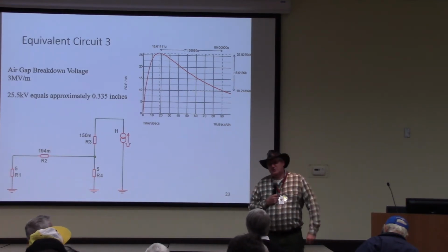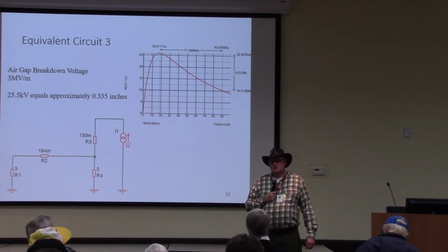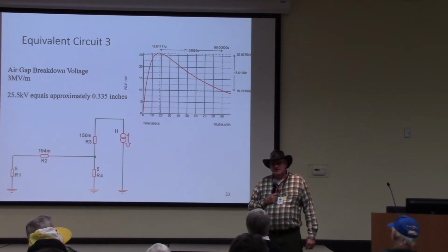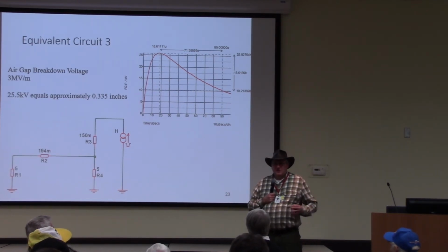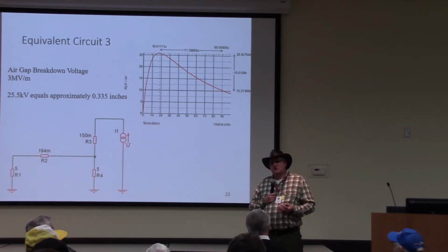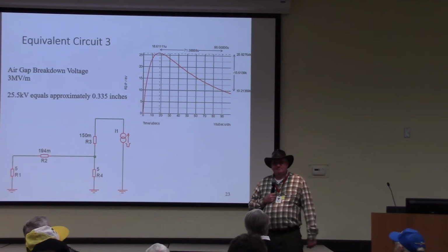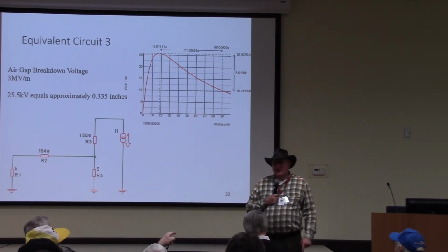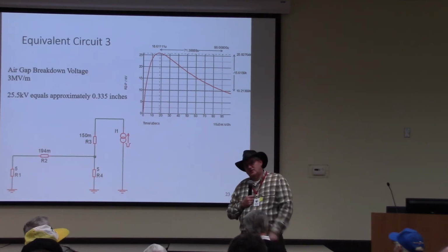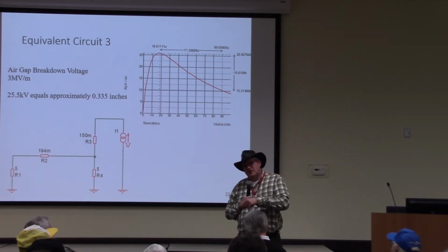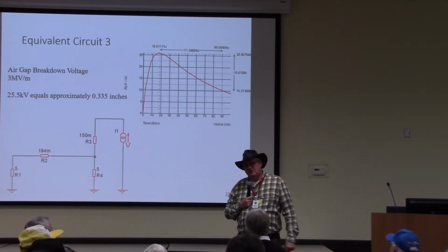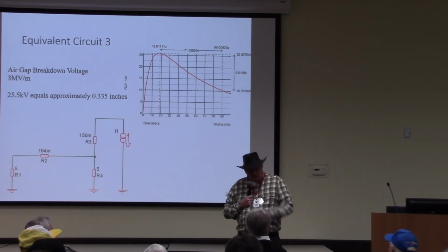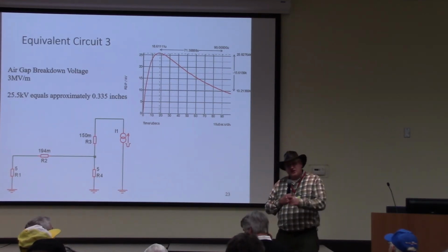You're improving it, but you're running the risk of bringing those currents and all inside your house. And when you penetrate your house, the wooden structure and all, if those wires go through or close to any metals and insulation, it's not as good as it could be if you've done it outside. Plus, the question is, those ground rods at that point, are they tied to the main ground rod coming into your power distribution system? Yeah. Okay, good. That's a key point.